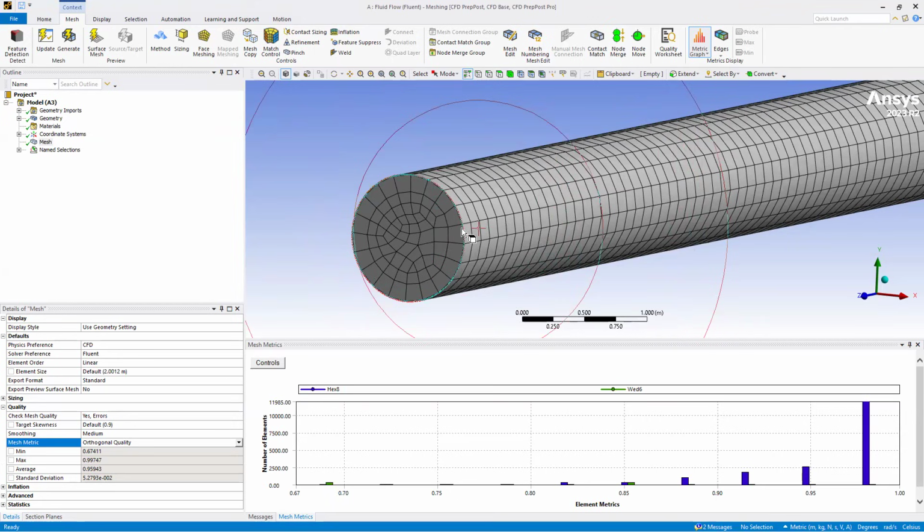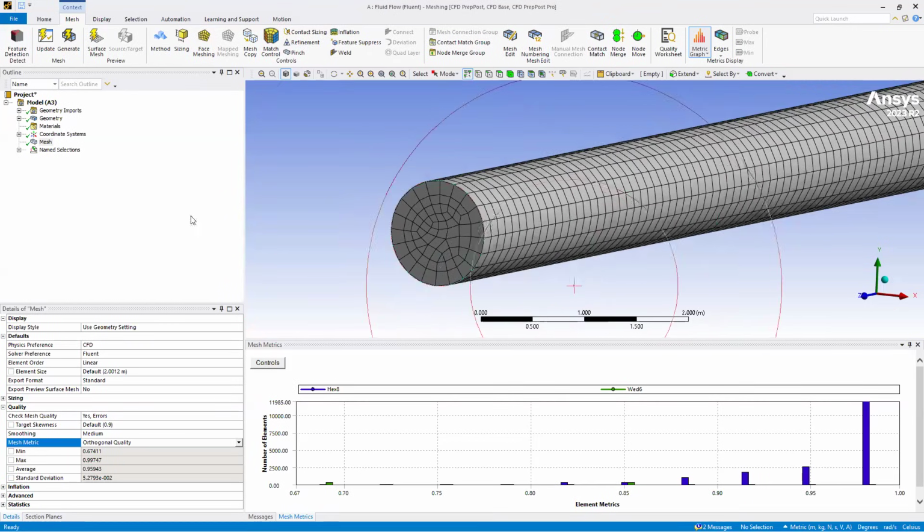And if the elements are skewed, the skewness will always be because of the geometry curvature. So divide the geometry into parts so that we can have more control on the element shape. So that is doable. For triangular mesh, this is mostly automatic. But then my suggested solution would be to put more cells in some location, or fewer cells in another direction. This will solve the problem. Okay, we'll see this thing. But first we must know what is required, what is not acceptable, and what we are trying to achieve. That is the first thing we should know.